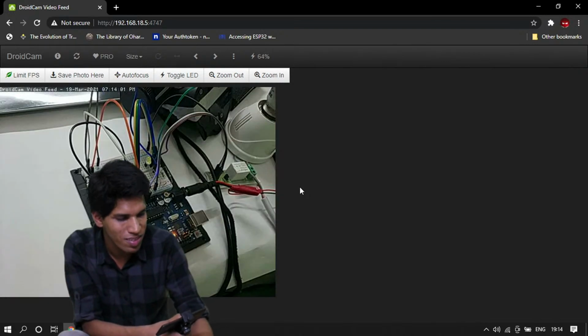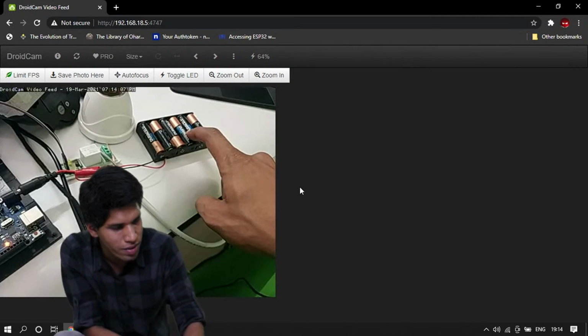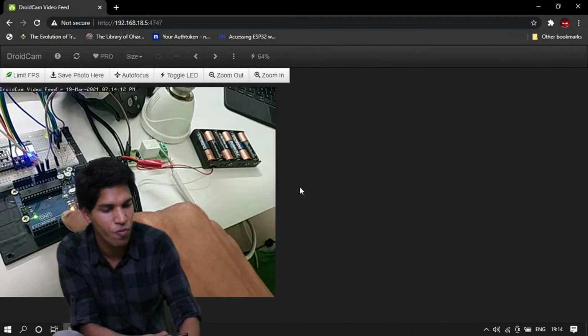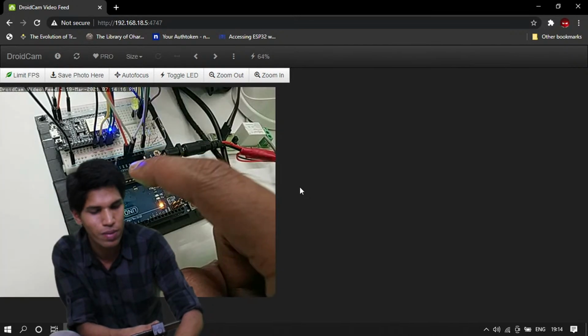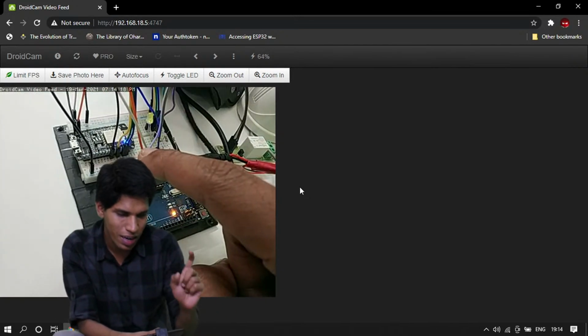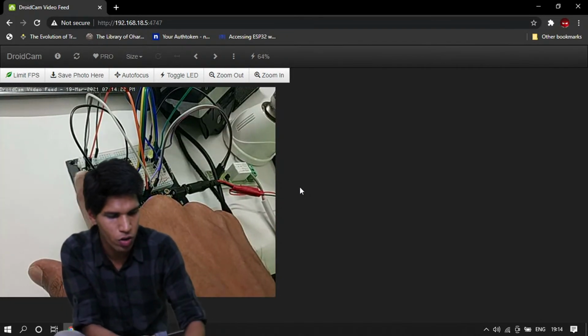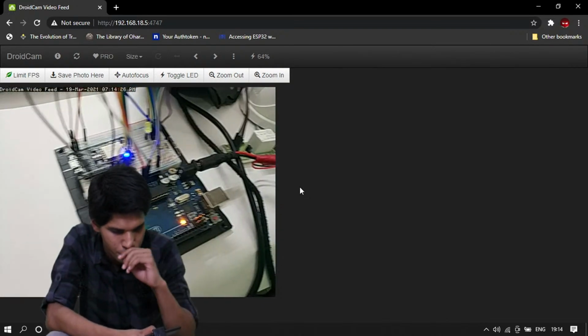So I'm using this 9 volt to power my Arduino, and on my Arduino there is a pin using which I can output 5 volts of power. That 5 volt is what I'm connecting to the Node MCU board right now. But you guys can directly use a 5 volts battery if you want. Don't worry about the Arduino here. Arduino is completely unnecessary in this example.